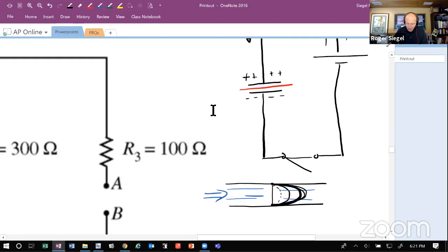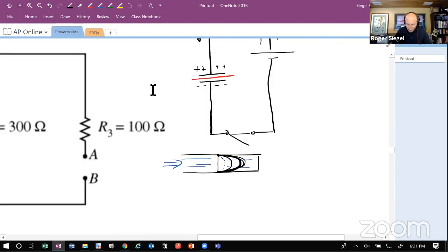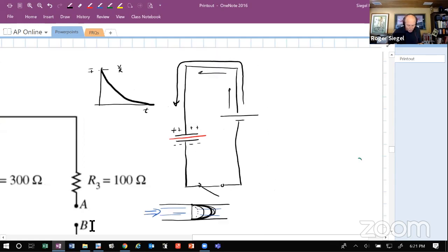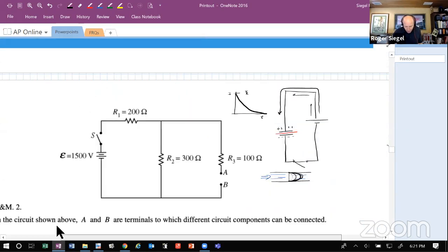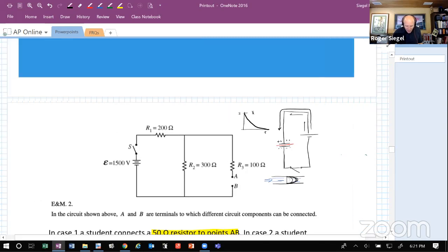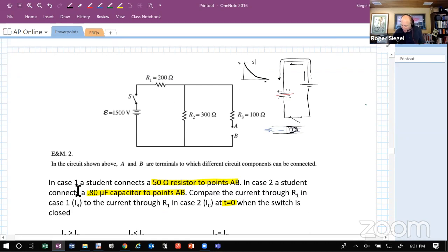And that's what happens here in this circuit. When we start the circuit, when we throw the switch on, this is current versus time. At the beginning, the current acts as if there was nothing there, as if there was just a wire, not nothing, a wire. And so this is V over R. That's the initial current. It's very important when we're looking at capacitor problems that we look at what the time is. When is this happening? In this problem, you can see at t equals 0.